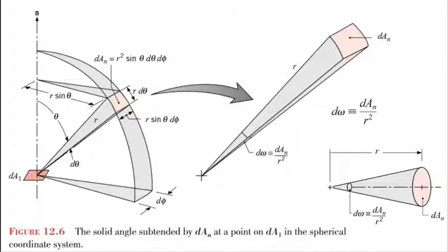That is, when you have an opaque surface emitting on one side, you will be emitting all through the hemisphere, and the total radiation will be the energy that is going through 2 pi steradians for an opaque surface. Okay, so that is usually the way it is counted. For emission, normally you look at only one side of the surface from where the emission goes. The other side is normally taken as unaffected by that for surface emissions.